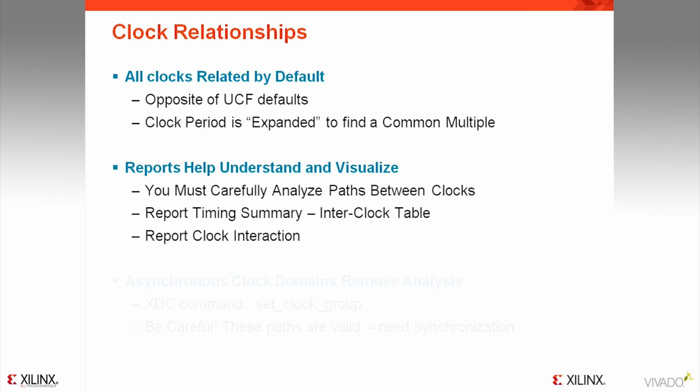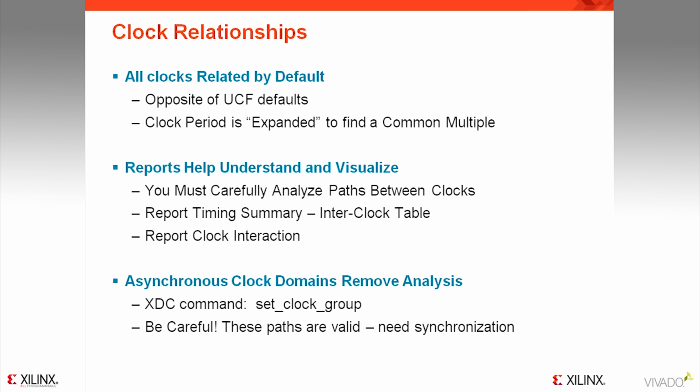Designers need to provide input to the tool if these clocks are supposed to be asynchronous, which means they have no known phase relationship, and edges can truly come at any time. The command to do this is the set_clock_groups command, and details of how to use it will be covered elsewhere. The important thing to note is that you're disabling the analysis of paths that really exist in hardware, so you need to be careful and ensure that proper design methodology for clock domain synchronization is followed. Either insert a chain of flops to synchronize, or use a FIFO circuit designed for this purpose.